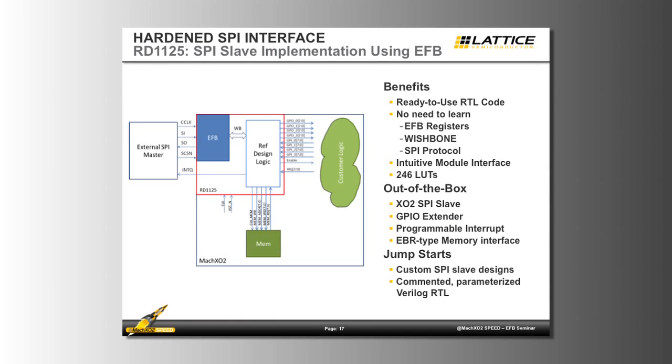The first section of this module is the SPI Bus Slave Interface Reference Design. It will allow the user a quick implementation of the hardened SPI bus with ready-to-use code. A possible application fit with this reference design is using it with the MachXO2 as an I/O expander for pin-limited microcontrollers. The reference design also includes a well-documented test bench with a SPI master, a memory module, a back-end interface, and the device under test or SPI slave.